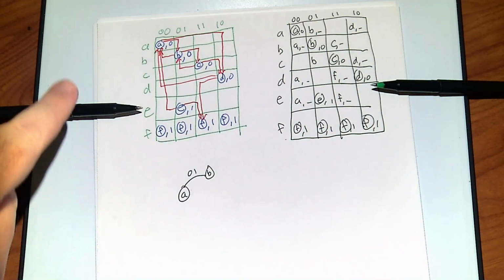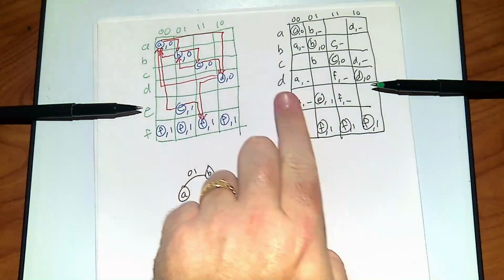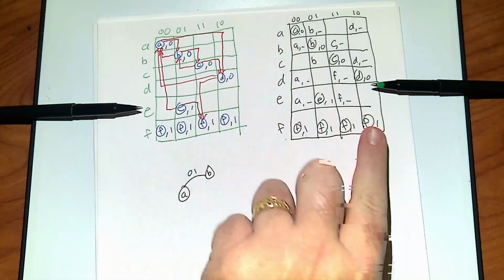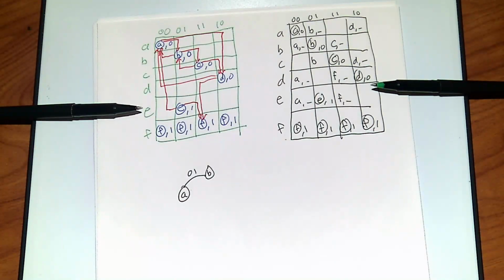I just had something which we said came from users. We just kind of drew the graph in the table. And then I encoded the stable states by the circles, and I did all the arrows by these non-stable states. Boom, done. I've got my first table of primitives. And this could be turned into a K-map type thing for circles, but we're not ready for that yet. Looking at this, can you tell whether or not any of these states are needed? It's kind of hard to tell.